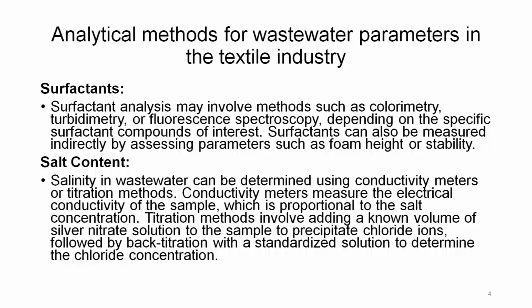So, by using a machine for turbidimetry, colorimetry or fluorescence spectrometry, surfactants can be analyzed, or even by making a physical test like looking at the foam height and stability. Salt content. Salinity in wastewater can be determined by conductivity meters or titration methods.